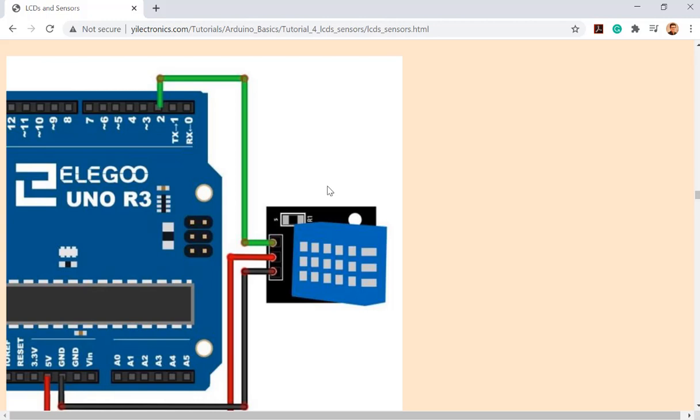So keep in mind, whenever you see a module with everything encapsulated like this, even though you know it's an analog device or analog sensor inside, they actually already have a digital IC chip which converts the analog signal into a digital protocol for interfacing with microcontrollers. Even though you can't see it, it's actually inside the module. That's more convenient because you only have one pin which can send both temperature and humidity data.